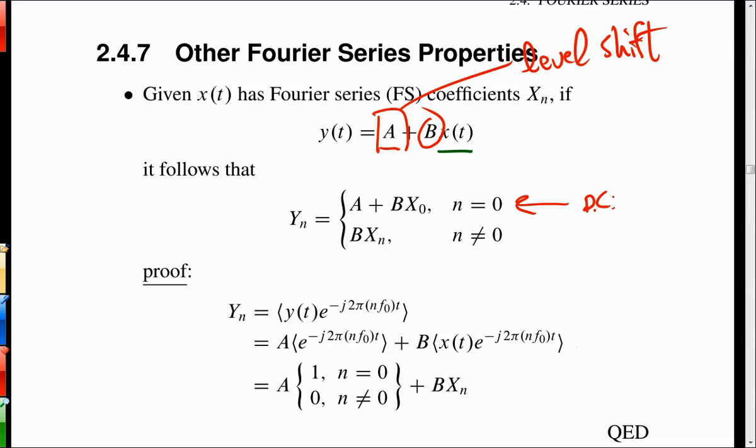Is that only the magnitude coefficients? No, this is the whole thing. Really? Okay. Yeah, because in that second homework problem, b was equal to -1, so it flips. And when it plugs in down here, it flips the phase on everything by 180 degrees, because a -1 would be 180 degrees phase shift. You have to think when you're doing a magnitude plot, though, -1 is equal to 1 at an angle plus or minus pi. So if you're doing the magnitude, all you really care about is that. If you're doing the whole thing with the phase, then you have to throw the pi in there.